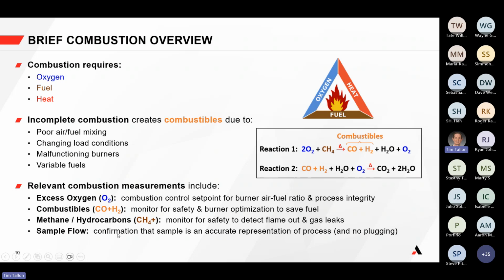And also from a combustion flue gas analyzer perspective, also sample flow, making sure that you have a confirmation that the sample is representative of the process and is in the right range, and that the analyzer itself is not plugged for whatever reason. So from a high level, as we get started into this webinar, I really want to make sure that we're reminded that every measurement has an important role that plays into the overall picture of the visibility of the health of the combustion process.